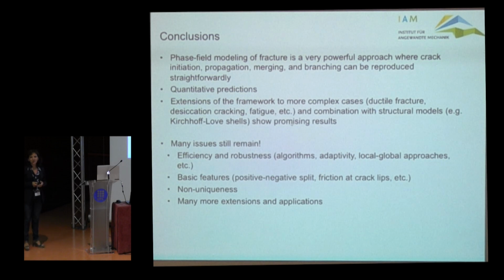So we can conclude that phase field modeling of fracture is a very, very powerful tool and a very flexible approach where you can model crack initiation, propagation, merging, branching, a lot of different phenomena in a unified setting on a fixed mesh in 3D. You can achieve quantitative predictions. You can describe extensions also to more complex cases, for instance, ductile fracture, desiccation cracking, fatigue. We are still at the beginning of that. And a combination with structural models is also feasible. For instance, I showed you Kirchhoff-Love shells. There is still a lot to do, but the results are very promising.